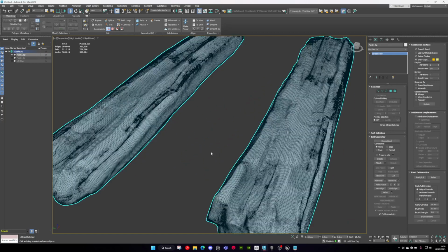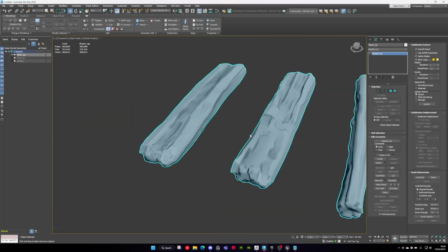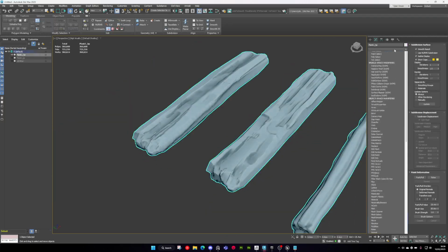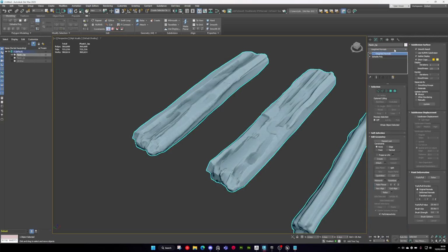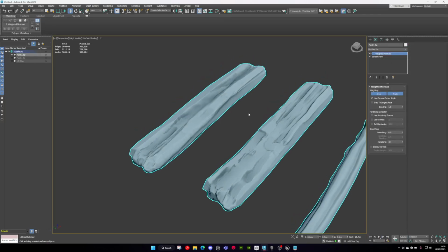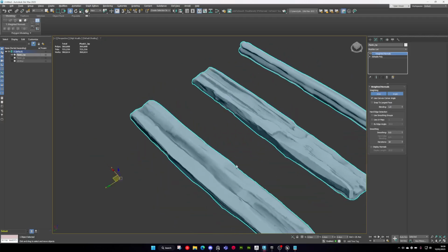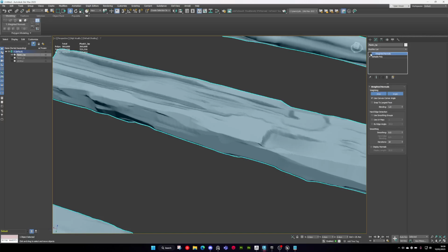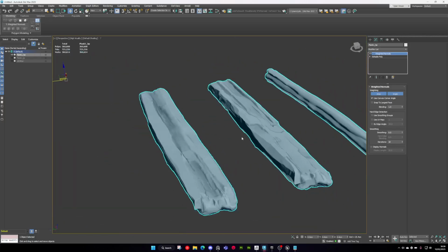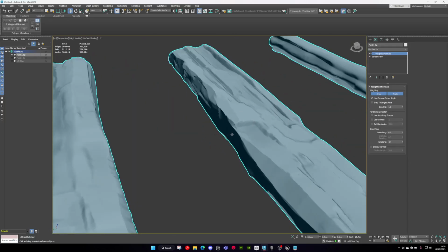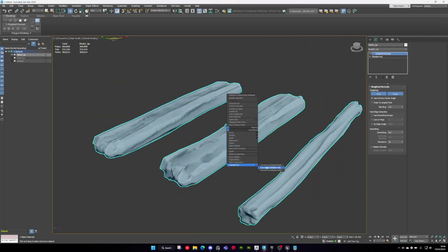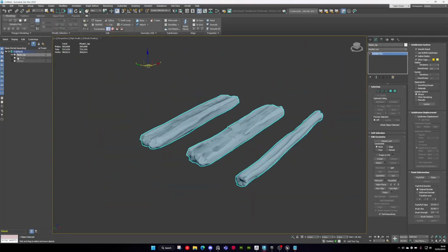Right, then one thing that is always quite good to do on your mesh, especially your high poly, is chuck a weighted normals on there, because ZBrush doesn't smooth your normals properly because it doesn't have smoothing groups. It just puts everything into one smoothing group. But with weighted normals, you get nicer shading based on the angle of the face. So we can do that on the high poly, but especially on the low poly.